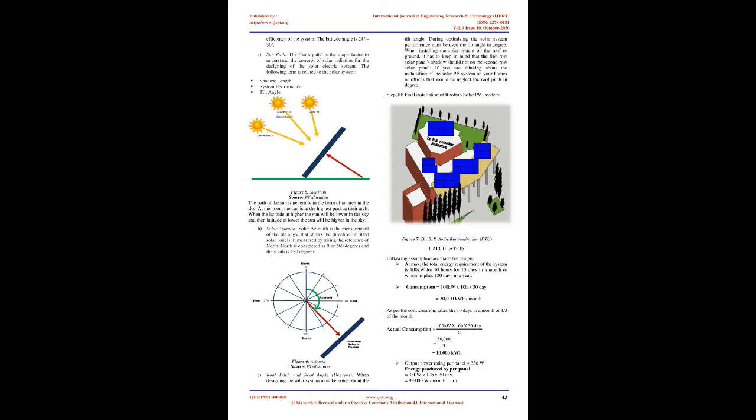In this step, firstly use the Google Earth tool to import the area from the Google map where work is to be done. You can also show terrain relief by clicking File, Geolocation, Show Terrain. After importing the image, you can set or place the image according to your design area, and then the resolution of the image can be maximized or minimized as suitable for your design.